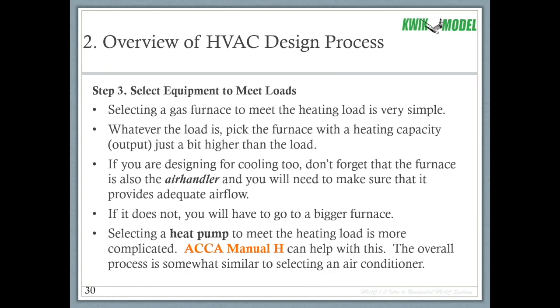Selecting a heat pump, on the other hand, is more like selecting an air conditioner. There are more things that come into play. Airflow, outdoor temperatures, and things like that do affect the heating capacity of a heat pump. So if you're going to get into that, which you probably will, ACCA Manual H will help you with sizing heat pumps. The overall process is somewhat similar to selecting an air conditioner.